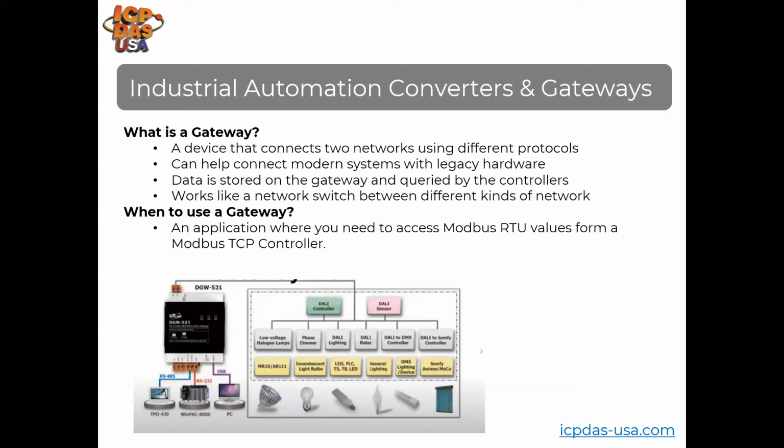These are some Modbus TCP-based programmable controllers. The PC running SCADA software. The controller software and PLC don't speak native DALI, but they're able to control the DALI lighting equipment for integration into the building management system.